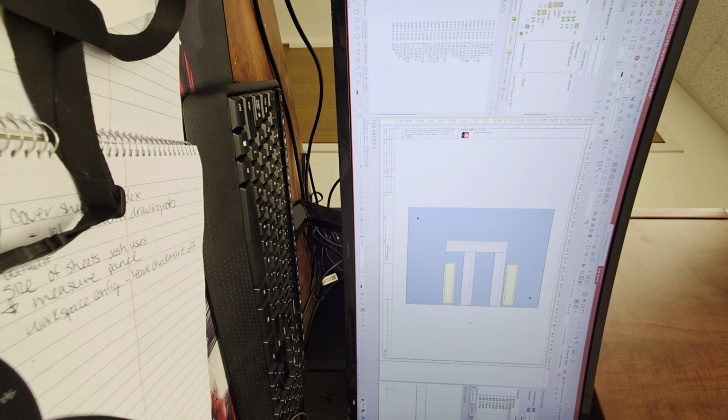Right? But if you say, all right, I'm not going to use ducts in my project as I don't need to see them, there are 2 things you can do. It's a workaround purely from a visual perspective, but it's a requirement for this automatic routing that takes place in this tool. These ducts have to be there just to route the wires from object A to object B. But from your perspective, you don't want to see it and you don't want to see it on your BOM, right? That's kind of your 2 requirements, right?